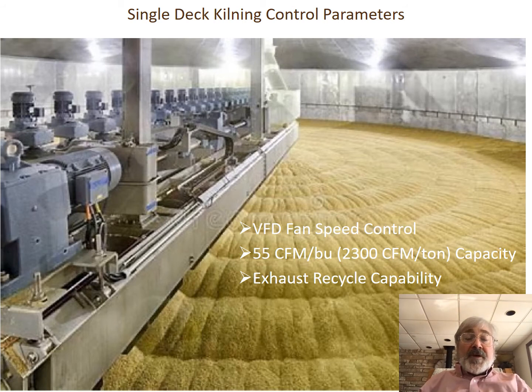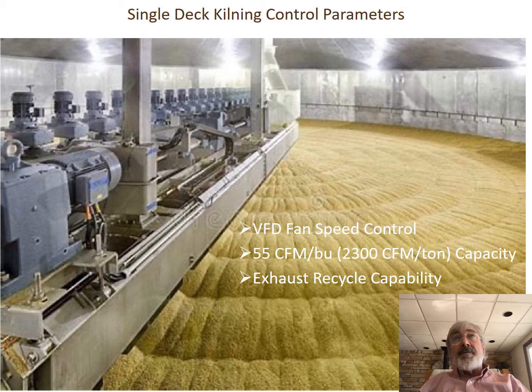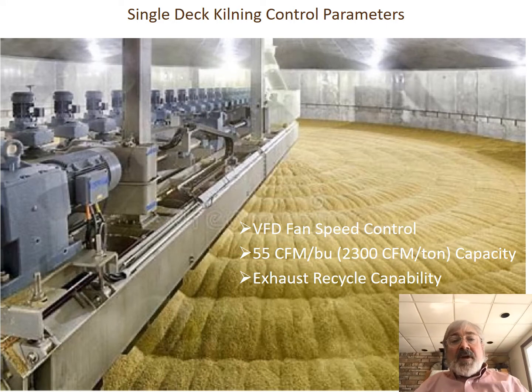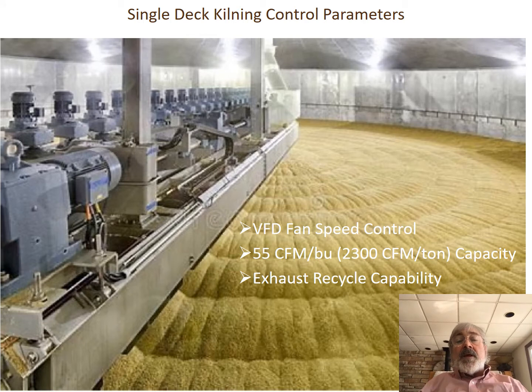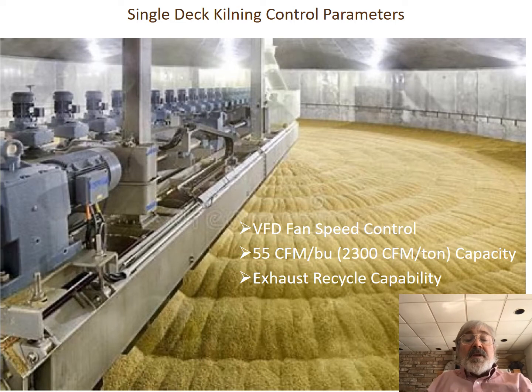Really good features for kilns today that weren't available 35, 40 years ago: variable frequency drive fan speed control. So you can lower your fan speed down to roughly, at best, 40% of your maximum capacity. I'm showing you a specific airflow capacity here, 55 CFM per bushel. That comes right out of Anheuser-Busch. In tons, that's a 2,300 CFM per ton capacity.